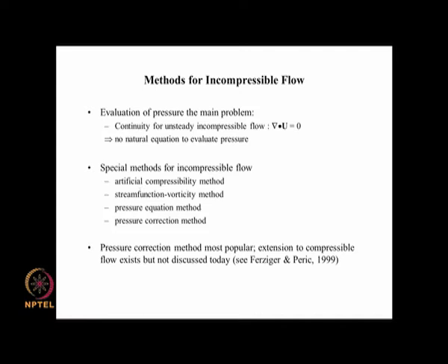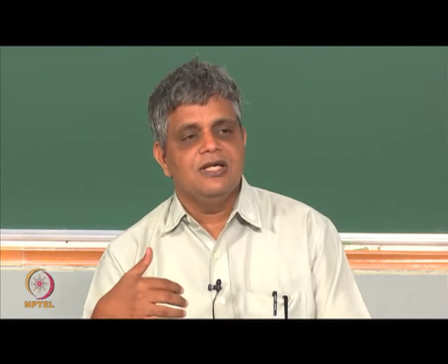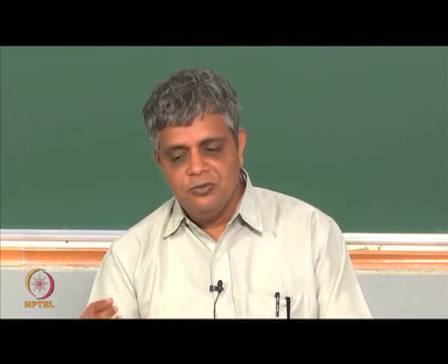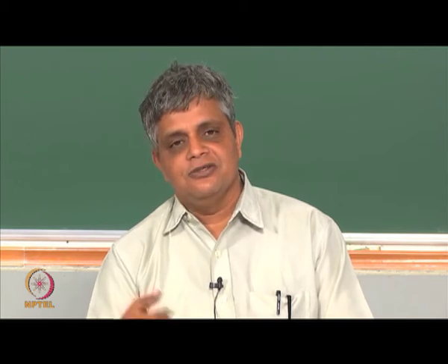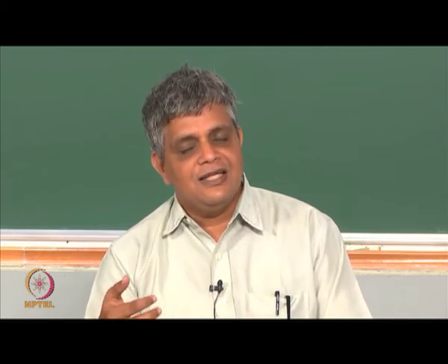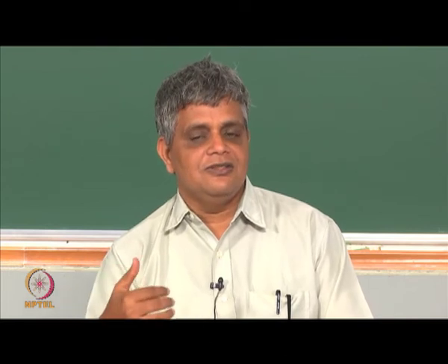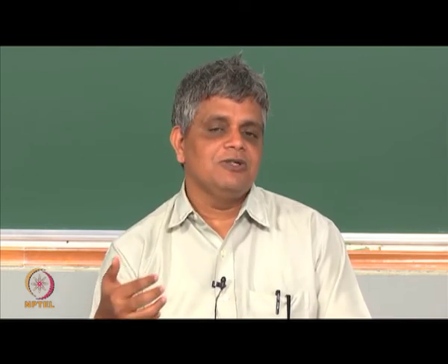If compressibility does not exist, if there is no relation between density and pressure, if there was a relation, then we could have evaluated the density from the continuity equation and gotten the pressure from the equation of state, which would be linking pressure and density through the compressibility. So, if there is no compressibility, then we could artificially introduce a compressibility and then create a linkage between the continuity equation and the momentum equations.